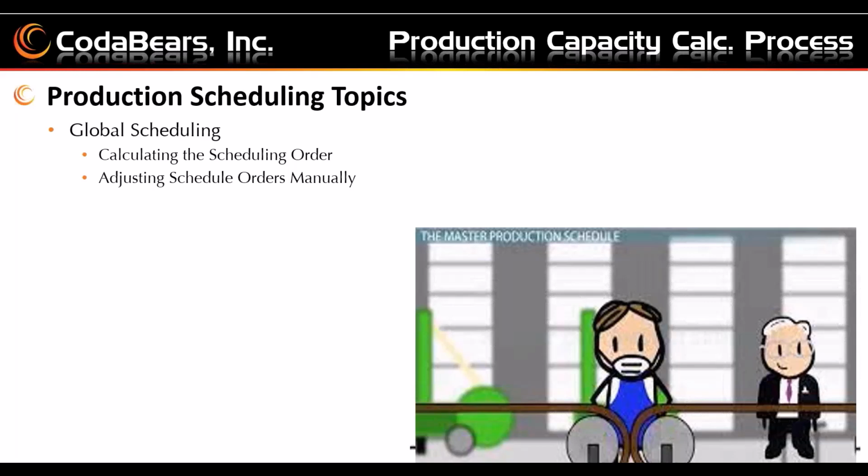One thing I didn't mention is, can I have both? Ding, ding, ding. Nobody asked that question yet. And that's a yes. So can I trick the system and have 4 welders and then create a 5th fake welder where I want to put my overload that's infinite? So Epicor will schedule my first 4 welders, which are real resources.